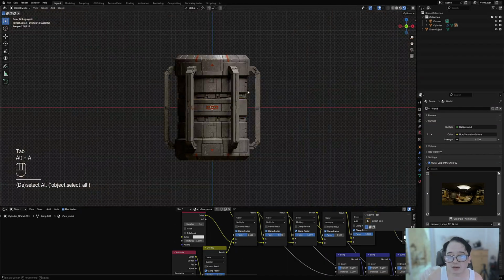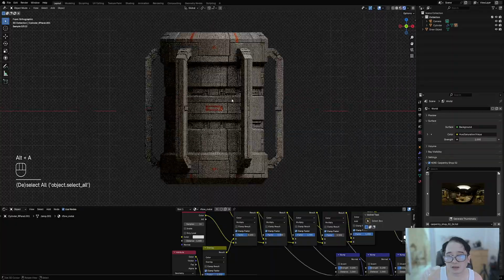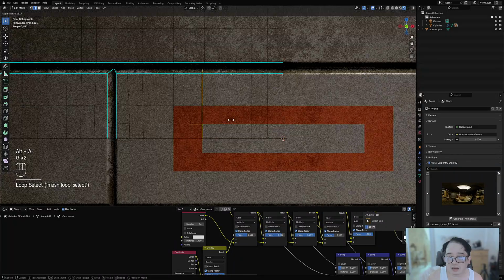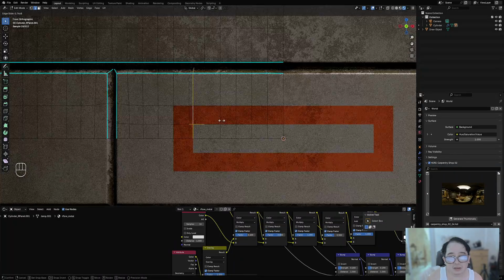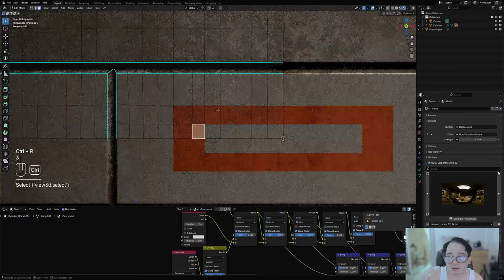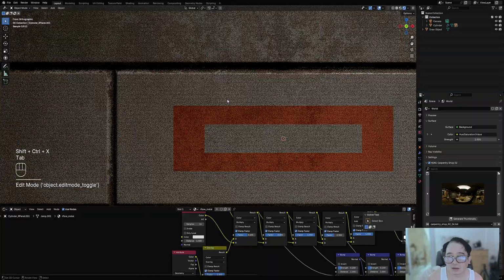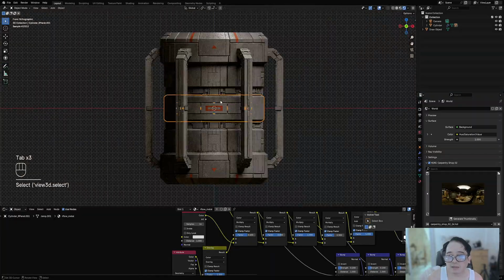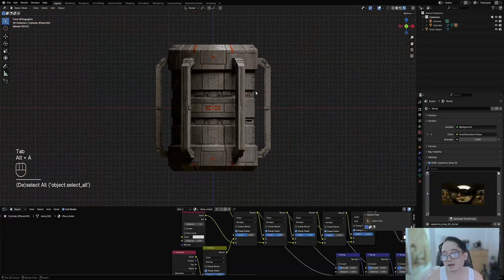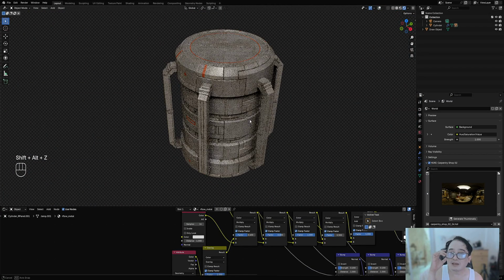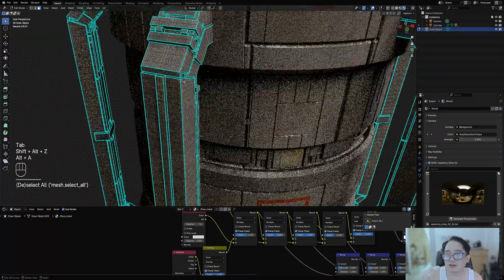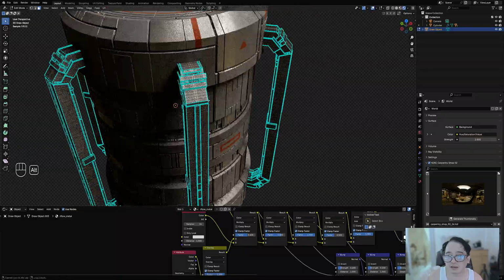So if you're wondering if somehow it doesn't work, that's because you need to set the object as the active object. Oh, yeah. We need to click it again. There you go. Just to add some basic color to your model using the vertex color technique.